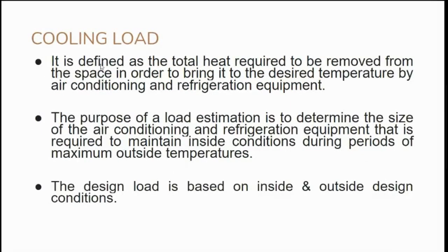Cooling load. Cooling load is defined as the total heat required to be removed from the space in order to bring it to the desired temperature by air conditioning and refrigeration equipment. The purpose of a load estimation is to determine the size of the air conditioning and refrigeration equipment that is required. So for a small space, around 1.5 ton AC is enough, whereas for large buildings, we need around 15 ton ACs. The design load is based on the inside and outside design conditions.